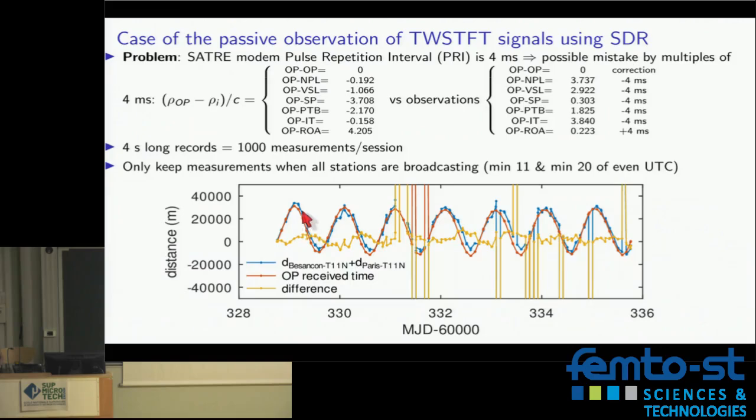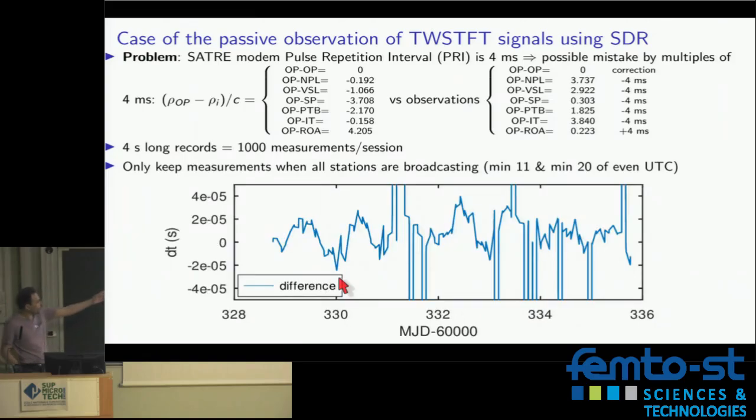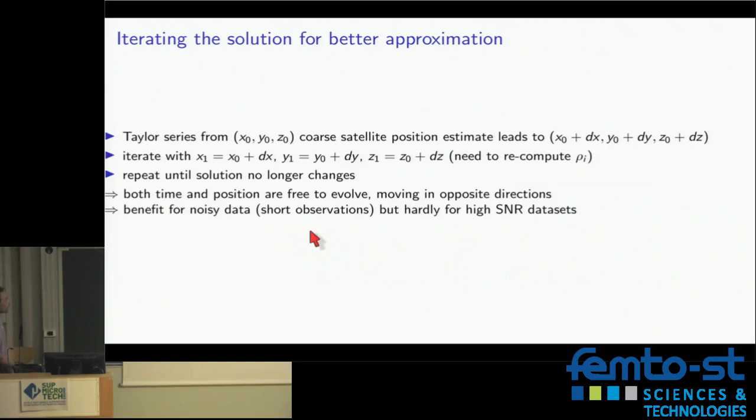So you have a plus or minus 30 microsecond, which is the satellite motion in space. But with the smaller dish that I have, and especially with a poor quality local oscillator, I can only reach plus or minus 5 microseconds. I cannot get the sub-microsecond result I was looking for. So math will not be enough to find a solution. We need to find something a bit better than just math. So that's your leftover. This is actually 20 microseconds, but if you take the standard deviation, it's going to be a bit less. So basically plus or minus 5 microseconds standard deviation on your time transfer. Okay, so at the moment, we only did mathematics, and we never discussed physics.